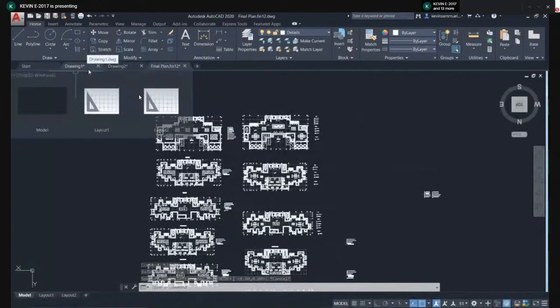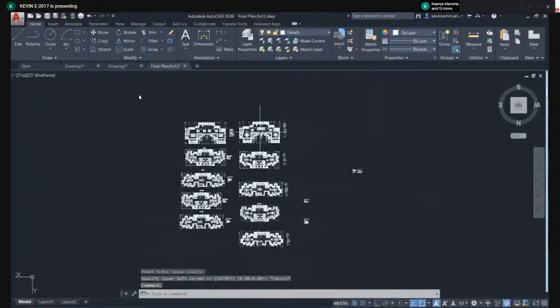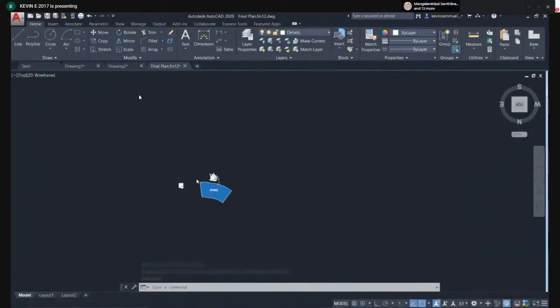Yeah, I think that's the frame, because when you are doing even more complex drawings, since the workspace is infinite, sometimes you might lose your drawing. See, just an example, I have absolutely no idea where my drawing is. If you set limits in a particular workspace, the drawing will just be within the particular limit, so there will be a restriction for you.